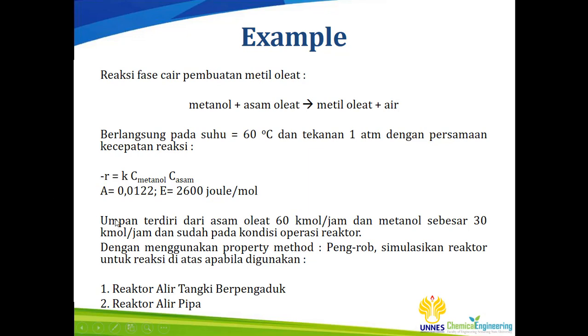The feed itself has 60 kmol per hour of oleic acid and 30 kmol per hour of methanol, and it is already at the reaction operating condition. And the property method used here is Peng-Robinson, and you have to simulate this case by using CSTR.